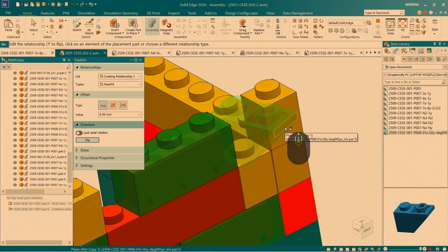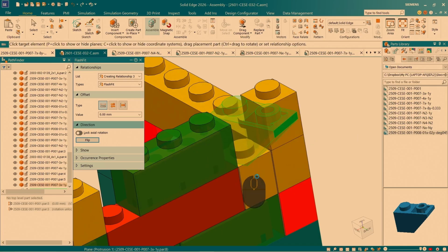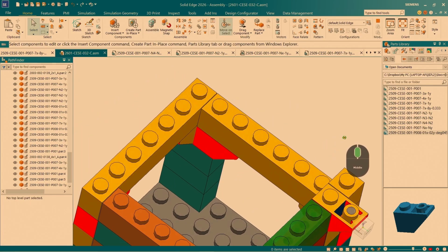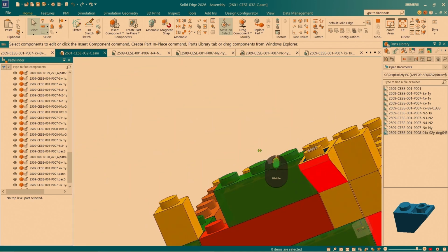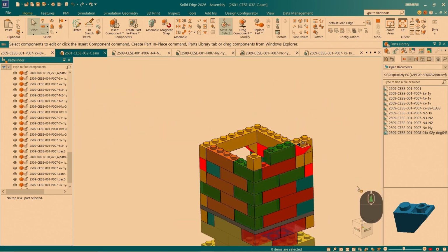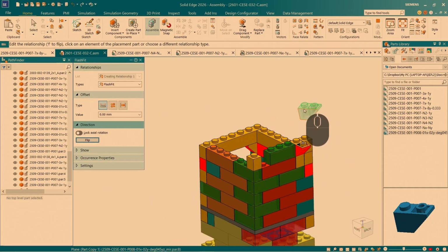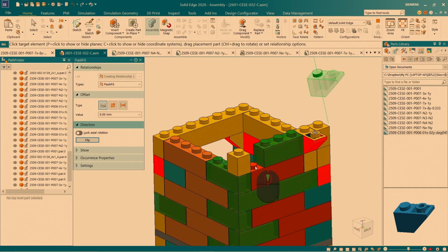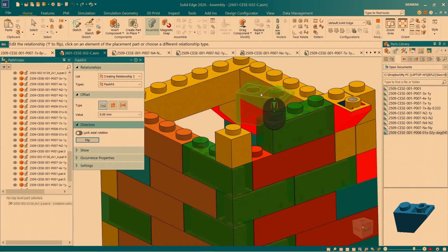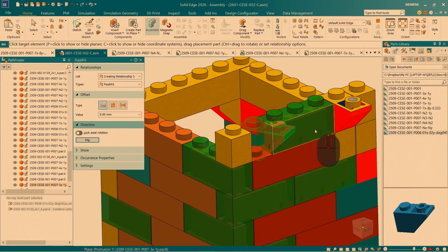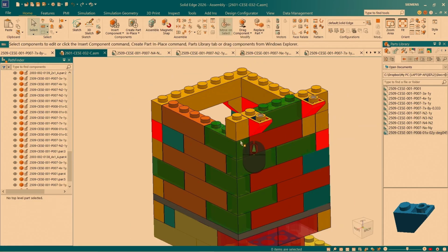We're just going to say flush fit between this face, and Solid Edge is picked up. It's a planar align with an offset, so that's perfectly brought in. We're okay. It just made those faces parallel. And let's do the same thing again and choose this peg here, and maybe this face here, and this face, and this face, and this face. And again, everything looks good.